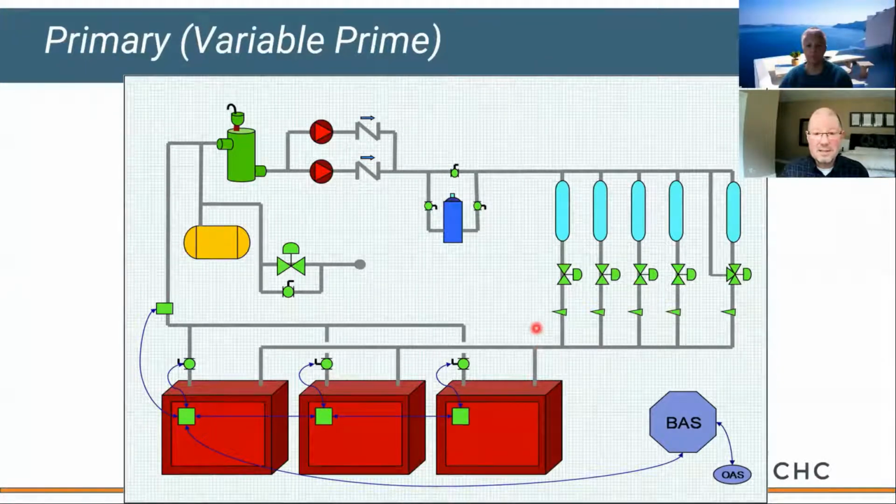Okay, so you'll notice that, hey, these system pumps are handling flow out here, but they're also getting directed through our boilers. So here's our cold water supply to each boiler, leaves warm and heads back out to the system. Now, a couple things that are very important with this. These little green valves shown, forgive the schematic, but these aren't pumps. These are motorized isolation valves. Very important, because we don't want flow going through a boiler that's not firing. Okay, so these really direct water flow as we need more or less heat out here in our system.